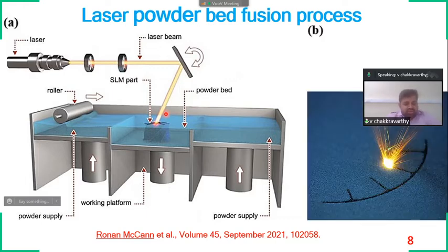Okay, so here we can see, as I told you earlier, in laser powder bed fusion technologies only selective areas will be melted and the remaining zones will stay unaffected. And another most common problem with laser powder bed fusion technologies is that whenever the material is being melted, some partial remelting zones will be there. In those particular zones, the powder won't be fused with the component properly, which will act like burrs. Okay, burrs are nothing but some extra projections on the component, which we generally call burrs.